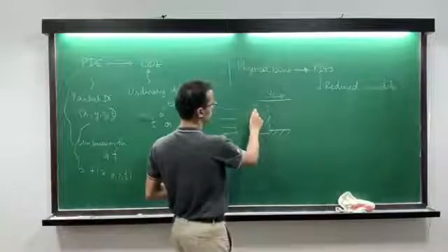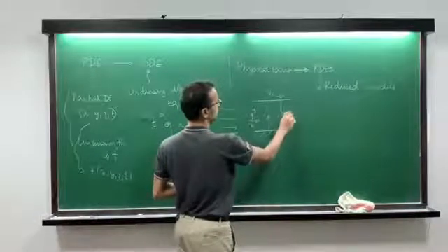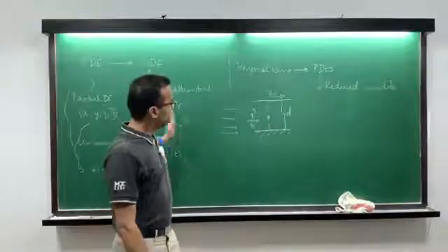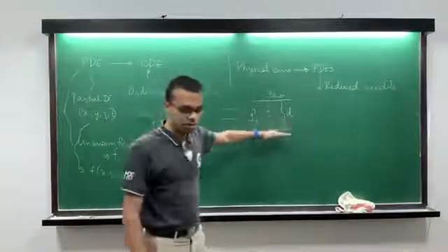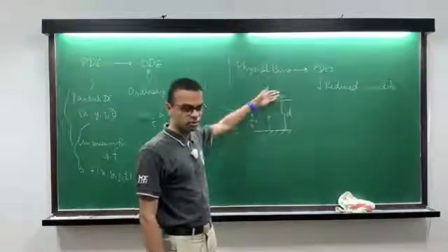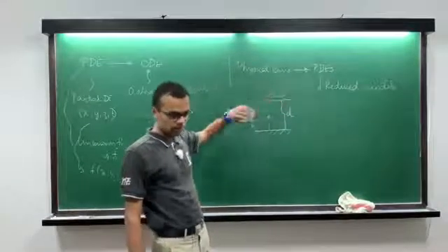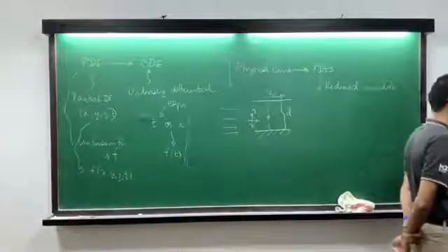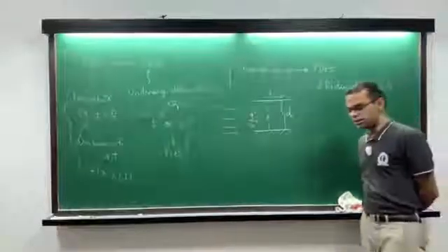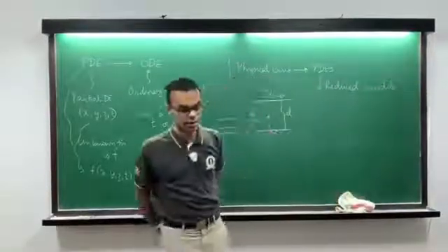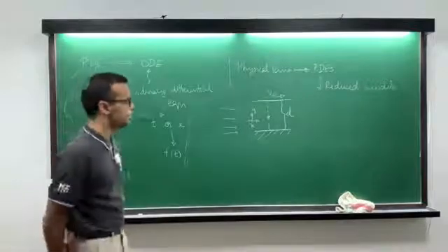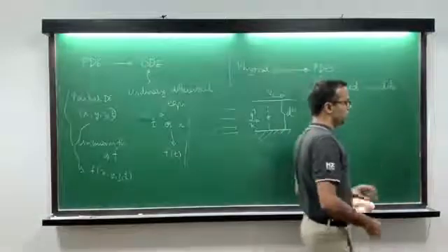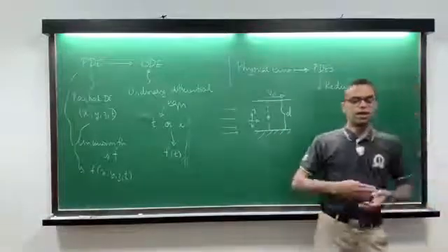Now this is a two-dimensional problem. Let's say the distance between the two plates is d, non-zero, and so you will have a gradient in the velocity going from the bottom plate to the top plate. Bottom plate is fixed, top plate is moving, so you should have a gradient in the velocity. Okay, this is a complicated problem. Again, it's governed by the same equation as the equation for heat conduction, turns out, the diffusion equation. But you can make an approximation. You can say, okay, if I want to know the solution, but I'm happy if you tell me the solution as t goes to infinity.